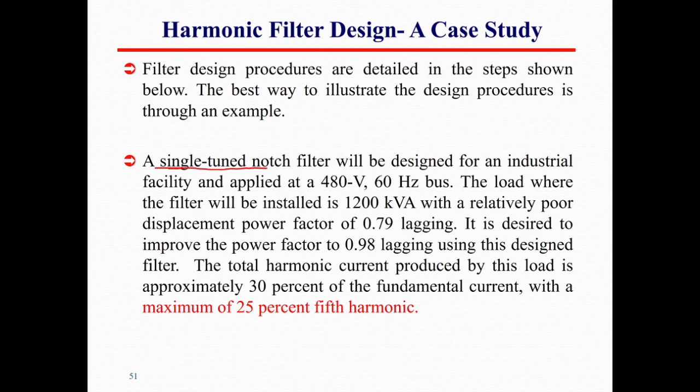The load where the filter will be installed is 1200 kilovolt ampere with a relatively poor displacement power factor of 0.79 lagging. It is desired to improve the power factor to 0.98 lagging using this designed filter.